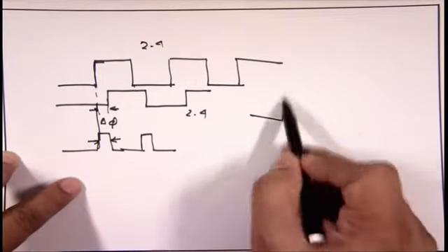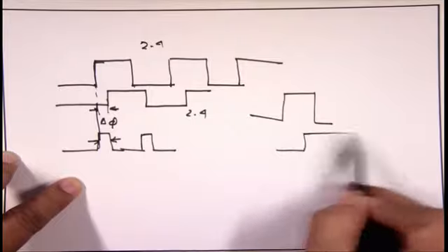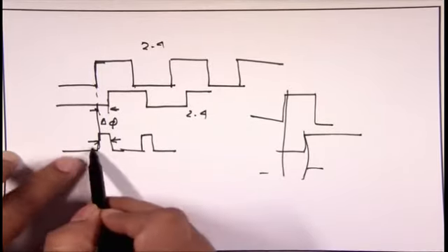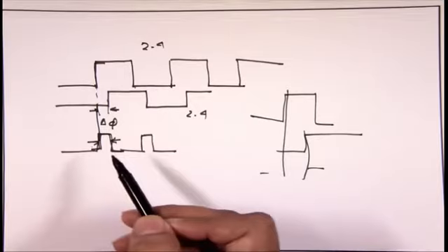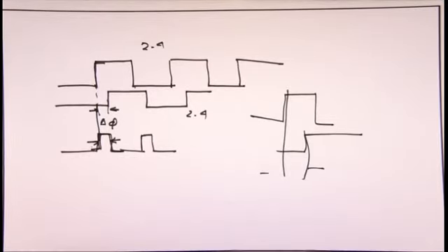If the phase difference is more, then you have larger delta f, that will introduce more pulse width. Now this is the PFD output. Sometimes an exclusive OR gate is not required, an AND gate will be used, because for a complete cycle I need only one pulse, not 2 pulses. I am just giving an example; you can use an exclusive OR gate and have 2 pulses, but you understand what pulse width modulation proportional to the change in phase is.